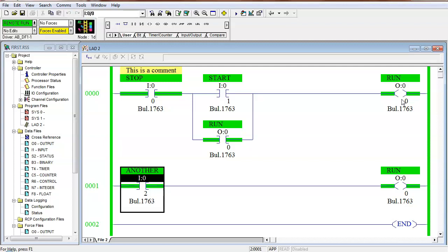So we used to do this on purpose, but what we would do, this was back in the days when PLCs were real slow. Now they update real fast. I don't know if y'all was in on any of the old computers that were really slow. They only ran one app. They couldn't multitask for one thing. And what would happen is that every once in a while the PLC would miss an input. So what we would do is we would duplicate the rungs. So the rungs would be exactly the same. You can get by with that, but we don't do that now. So the rule is don't use the same output more than what? One.